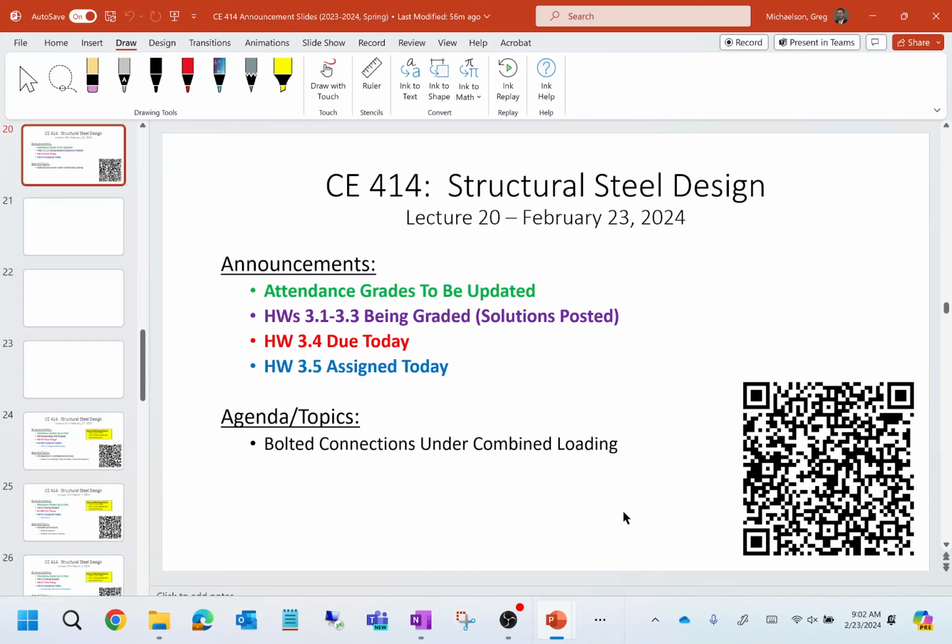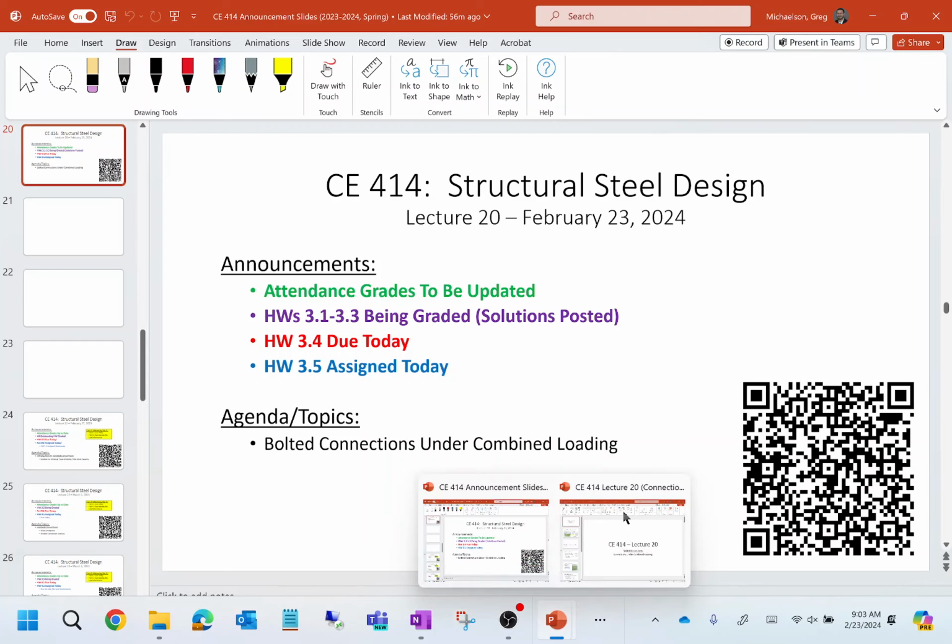Okay, still working on catching up on homework. The workable gauge table, I think, like we had some discussion before class. Other than that, the homework went well, but did everybody seem to kind of navigate that all right? Again, that workable gauge table was really only meant to help you place the bolts transversely, but transverse placement doesn't really affect bolt bearing capacity calculations. It's the longitudinal placement, and that didn't change. That's just edge distances and spacings and whatnot. So, okay.